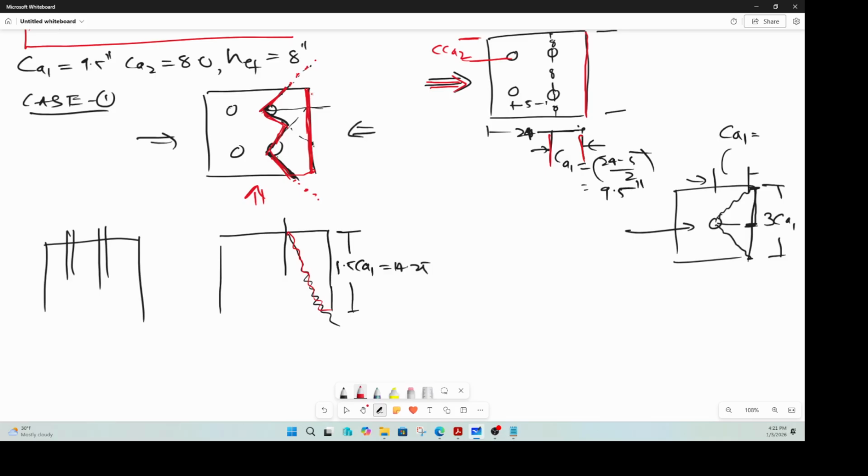Because there's no concrete there, we assume that that is the width of the failure surface, which is this width here, right? And in this direction, that depth is nothing but this depth here. So this is the projected area of failure. Okay, in the code, this is called AVC, projected area of the thing.